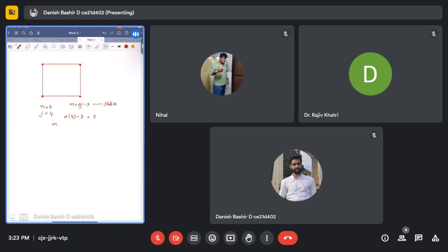So M is less than 2J minus 3. M is only 4, and 2J minus 3 is 5. So there is a lack of one member.